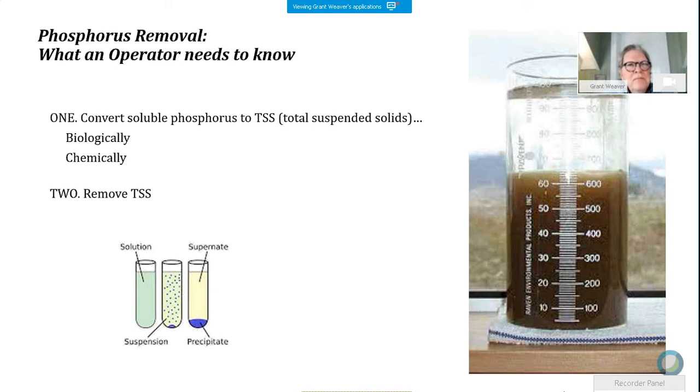And fine screening is now becoming really nice technology so that a lot of plants are being built without primary clarifiers, right? So if you have primary clarifiers, look to minimize the use of the primary clarifiers. There's some bigger plants that actually burp the solids back out of their primary clarifiers. They allow them to settle and then basically backwash them up so that they maintain as much of the BOD that's coming in the front door.